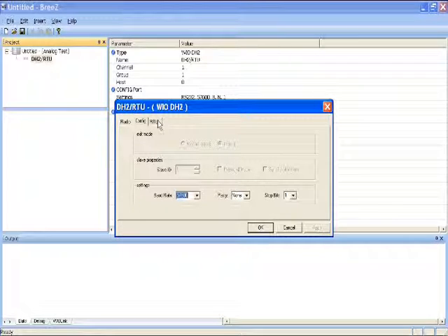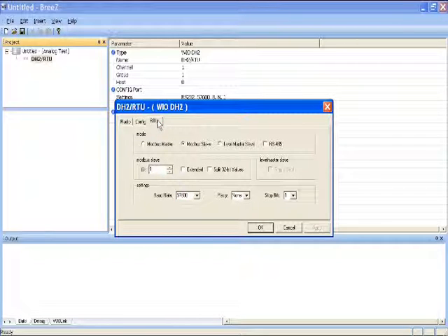Then go to the RTU tab. This is signifying the 6-pin Phoenix connector in the front of the DH2, which can be wired for 232 or 485. If using 485, check this box. You are a slave. You will ID the slave as needed. If you need extended registers, you will check this box.